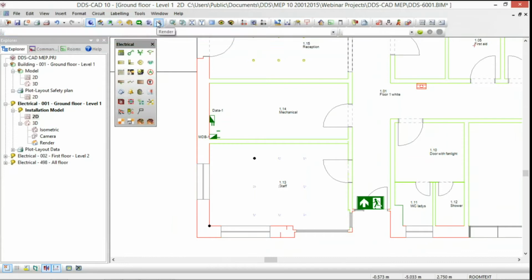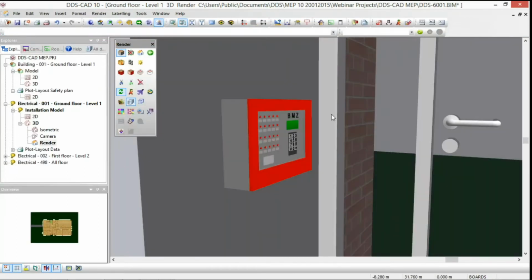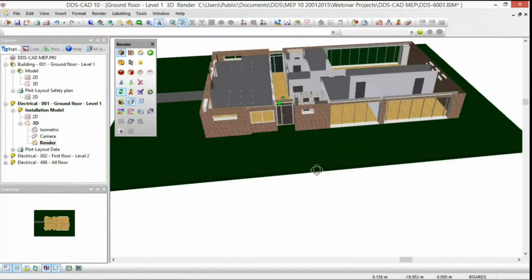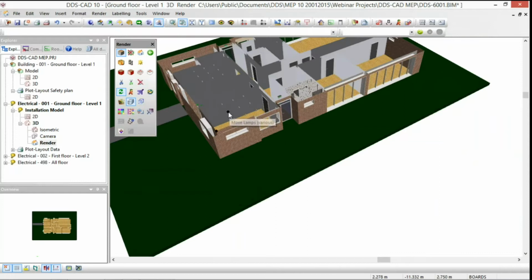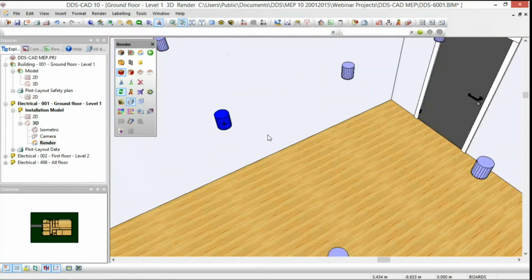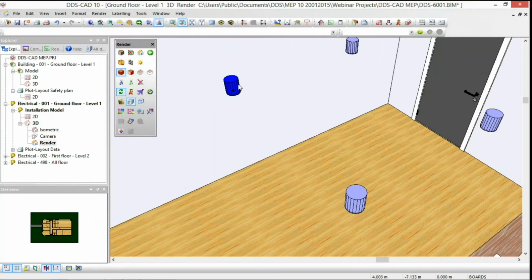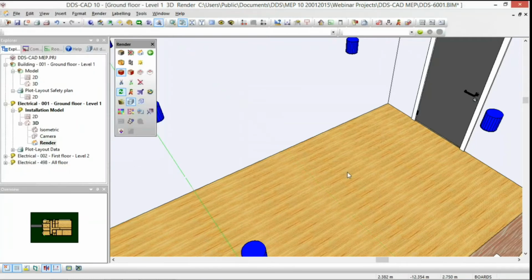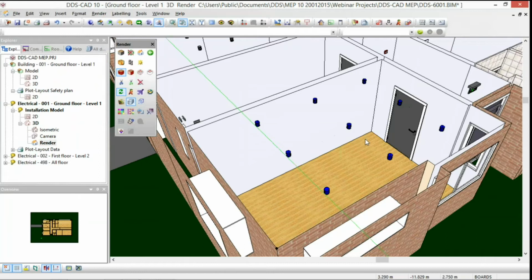If we switch to the 3D elements, and I will select based on my last point, I will make a selection to the lamps. We will see them as a group inside the room, and the lamp types itself are connected. So if we select the room, it can still be manipulated. So if I would like to change my offset to 1.5, we can see also in 3D that this offset is immediately responding to my changes.